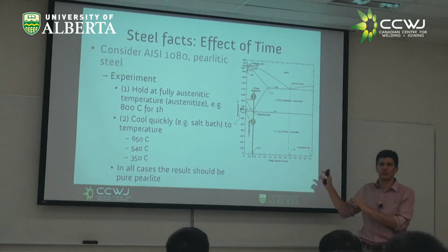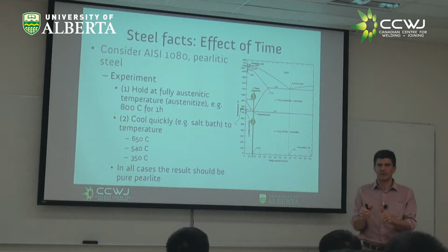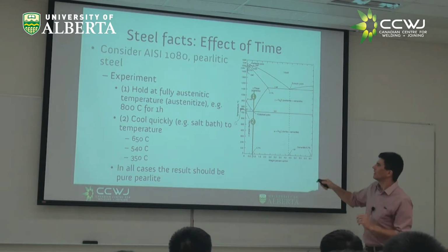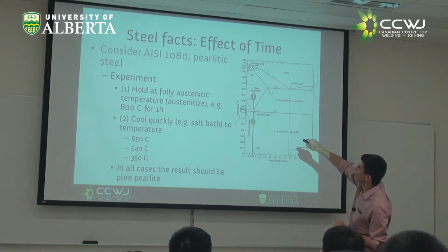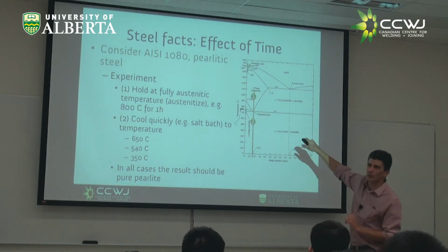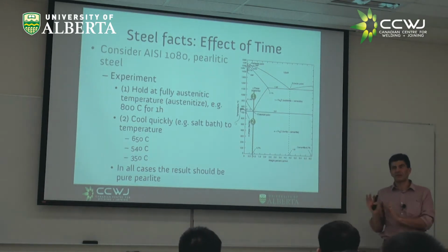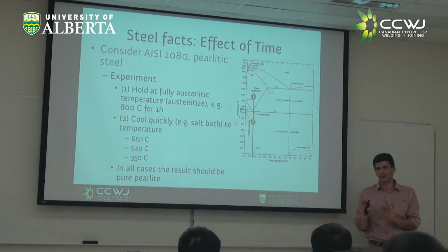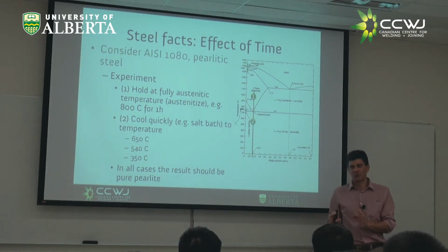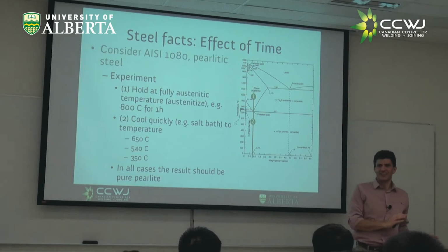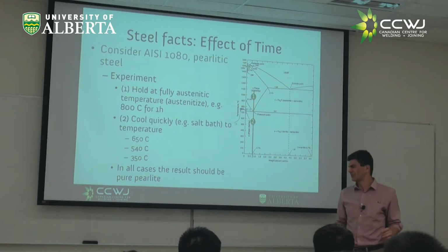So the whole microstructure here should look like all fingerprints, right? No primary ferrite, just fingerprints. Very easy. And there is no intercritical region here. It just goes from one to the other, right? This is a very easy transformation. By the way, you seldom want to weld this type of steels. We might be getting a project in which we do it, but they're not the easiest ones to weld.